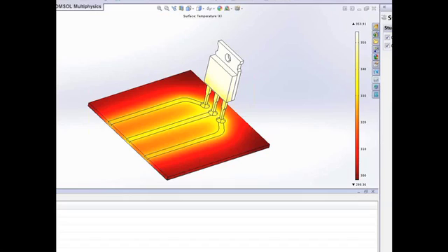But for the parametric sweep, you would just select parametric sweep, which brings up the settings for this feature. And notice also that it has been added to the left here under the study node. So now we can do a parametric sweep in the model. In this case, you need to select which parameters you would like to control.